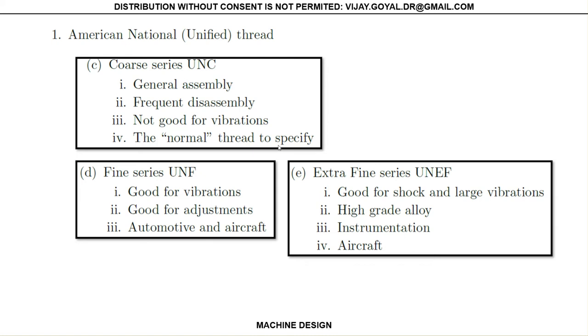If it's a little bit loose or not fully tight, and you cannot tighten it because you want to assemble and disassemble, then in those applications it's not good for vibration. Okay, and the fine series has a better adjustment and better engagement, which is very good for vibrations. But the extra fine series is much better for vibration. It's a high grade alloy. So if you're working with high temperatures, one of these two could be a possibility. This is mainly used for the aircraft industry. Here we use automobile and aircraft as well.